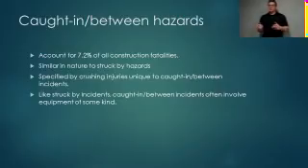These occur in what we know in construction as pinch points, and they oftentimes also involve equipment. If you imagine the swinging bucket of an excavator, somebody digging up against a wall, and somebody walks between that wall and that excavator, and the operator doesn't see and crushes him against the wall. That happens semi-often, and that's why we see so many caught-in or between hazards.